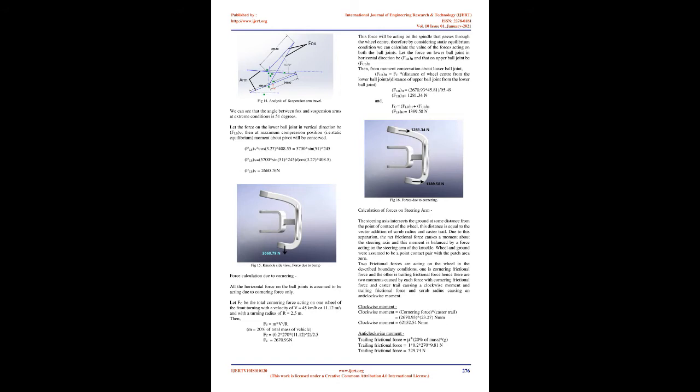Designing of the knuckle was a complex task as it is included in unsprung mass, so it has to be lightweight and also it has to withstand various forces in off-road conditions, so we had to design the knuckle in such a way that it would give the best strength to mass ratio.